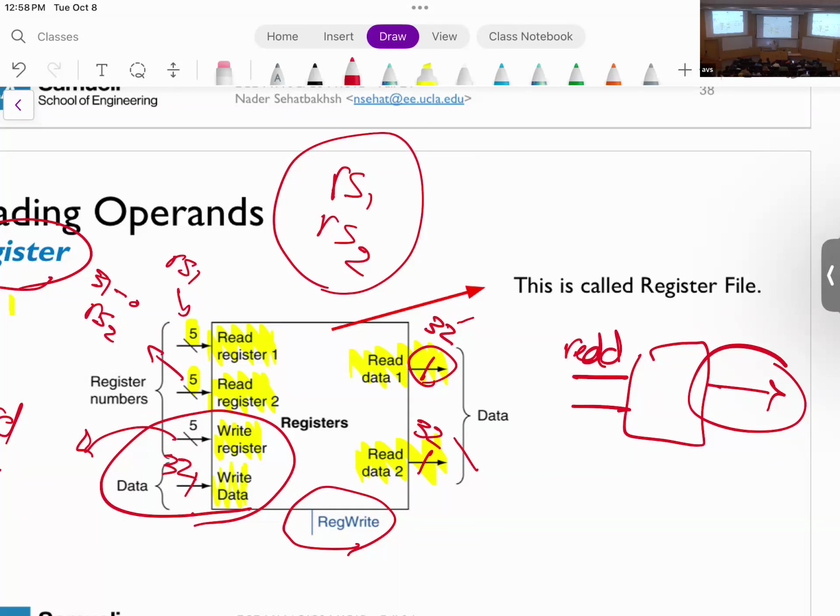So we're going to design it in such a way that if you read things and they're not relevant to us, we're going to discard them correctly. That's why we actually have write enable, because imagine that your instruction didn't have an RD, a destination register, and you're providing data to that. You would write to arbitrary registers that you were not intended to. That's why we always control this with the write enable.